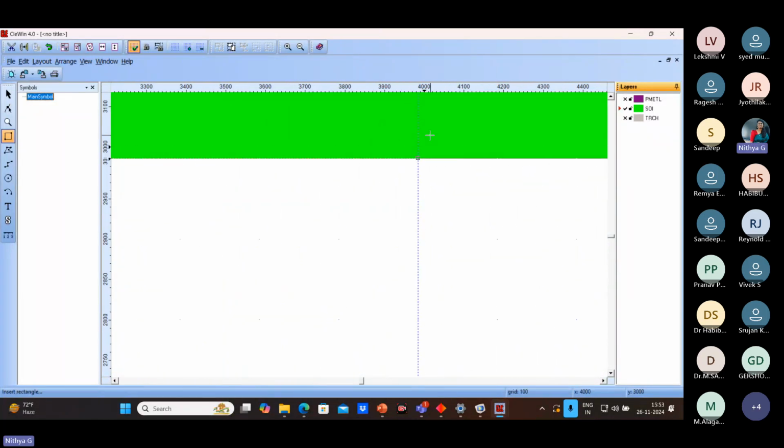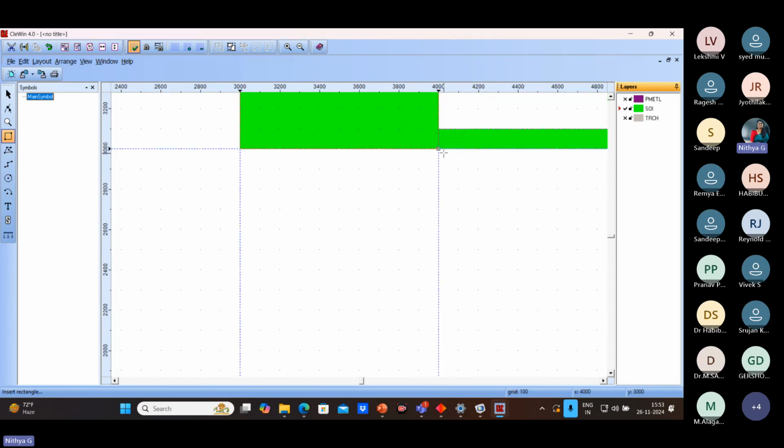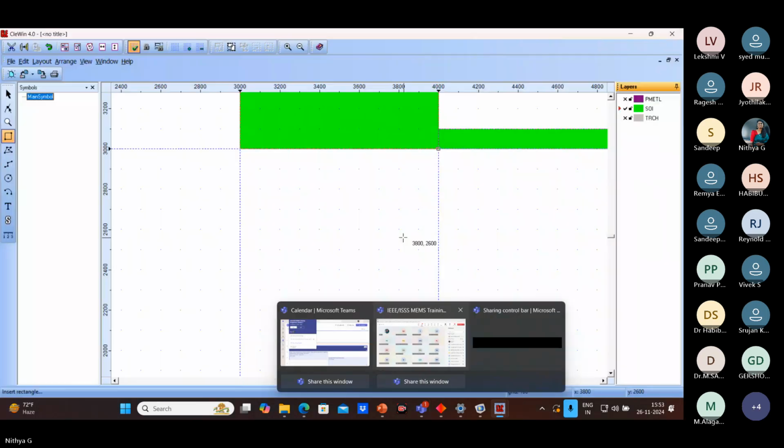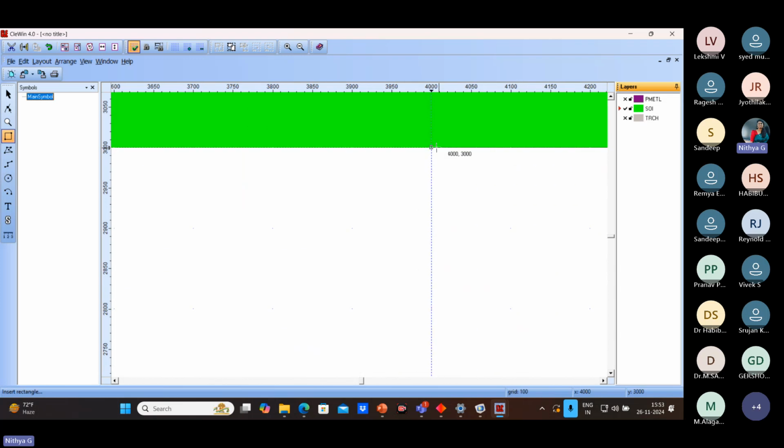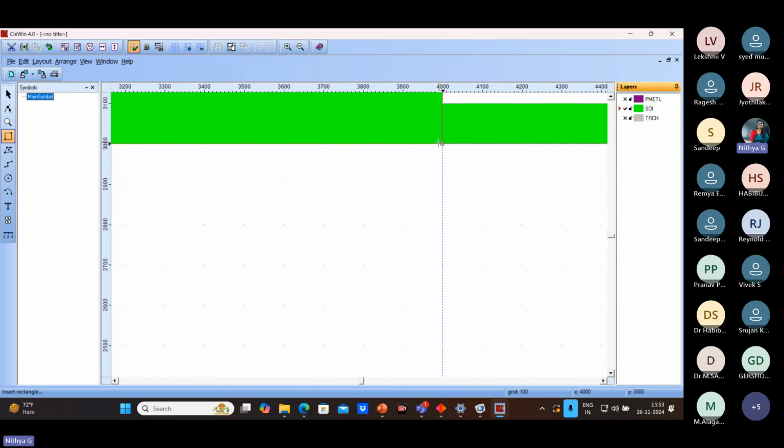Okay, you can see here, this again will lead to some fabrication error. So it is better to have a 50 micrometer gap from the edge. So please remember this. You cannot have anything exactly touching the end points here. There should be a minimum of 50 micrometer above which you need to create your beam.